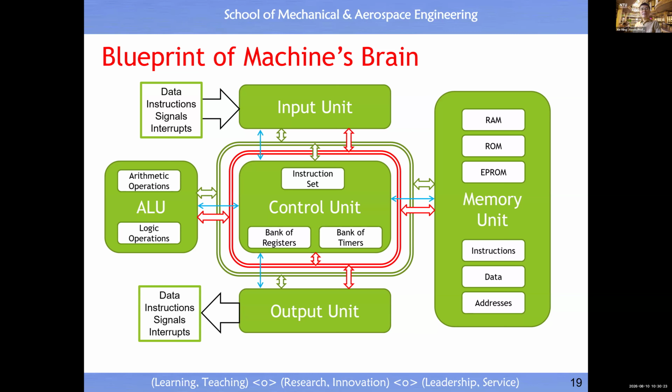Yeah, I just continue. Now you see we have the address bus. This is another terminology which is new to you. Bus does not mean transportation bus. Bus means a set of lines which enable the flow of a byte, 1 byte, 2 byte, 4 byte, or 8 byte. If the set of lines allows the flow of 1 byte, 1 byte means 8 lines or 8 bits, then we call this an 8-bit microcontroller.